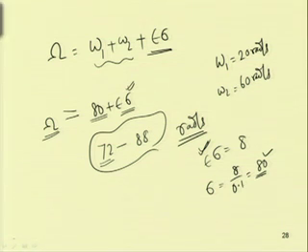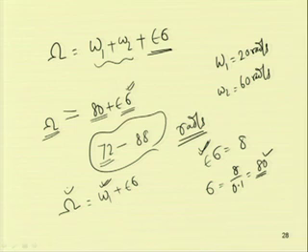Previously I told about the primary resonance condition, that is omega equal to omega 1 plus epsilon sigma, when the natural frequency is nearly equal to the external frequency. So, in the case of forced vibration of the system, we can have the primary resonance. This is primarily observed in the case of the linear system, but in the case of a nonlinear system, in addition to this primary resonance, one may have secondary resonance. For example, one can have the subharmonic oscillation or the superharmonic oscillation.